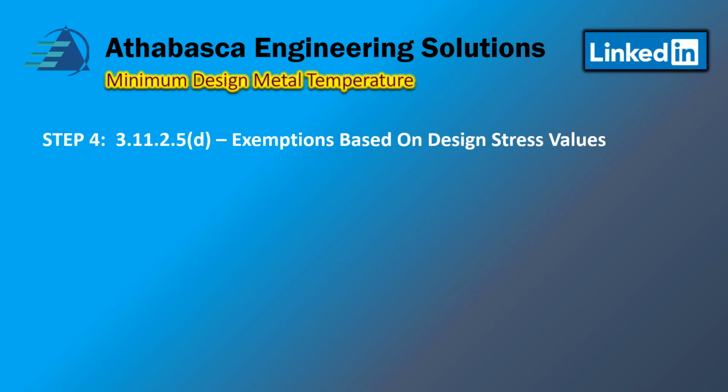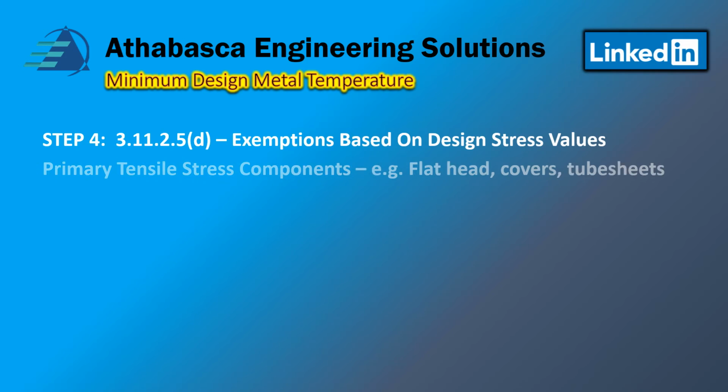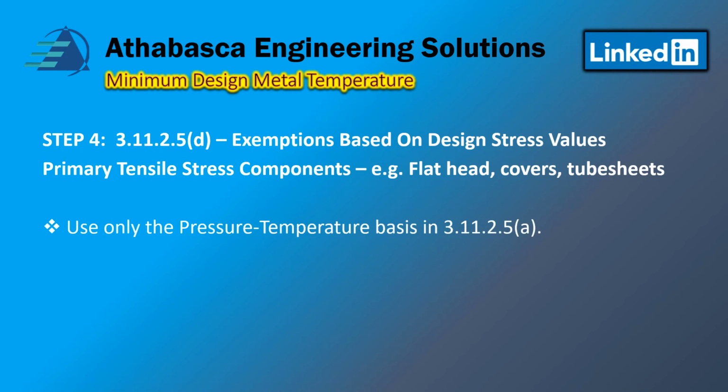In step 4, which is part D, they talk about the primary tensile strength components, which includes flat heads, covers, and tube sheets. We are only allowed to use the temperature basis ratio, which remember we showed 3 of them. Basically you use 3.11.5A for that relationship.